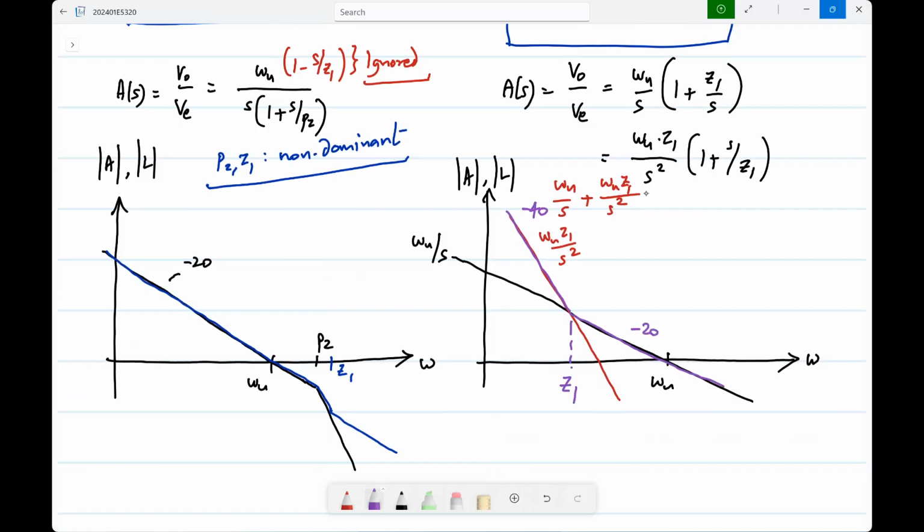Now, as you know, these are all different ways of saying the same thing. The Nyquist plot, in which quadrant should it enter the unit circle for reasonable stability margin? In which quadrant is it? Third quadrant, right? That's what it always does. Okay.